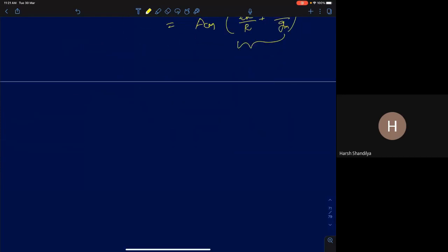Now, in most analog and RF systems, generally we define a parameter called signal to noise ratio. Most circuits have noise associated with them. It's a metric that tells you how good the system is. For example, in an audio system, there can be some ambient noise. If the audio signal is very low or equal to the ambient noise, then you won't be able to hear the signal very well. So there will be some noise level here. You want your signal level to be much higher than the noise level.